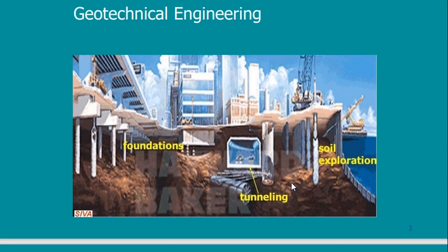How can I know this type of soil? I will go to something else called site investigation. Before constructing any of these things on top, I will need to go to the site, dig a few deep holes, take samples, test these samples on the site, and take some of them to the lab and test them. When I test them, I know what is the type of the soil, what are the constituents, what are the percentages of these constituents, and then I will need some equations.